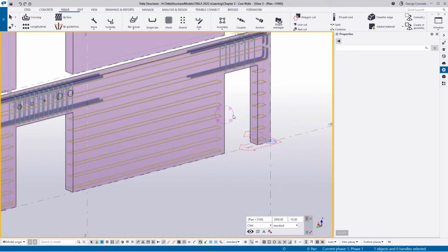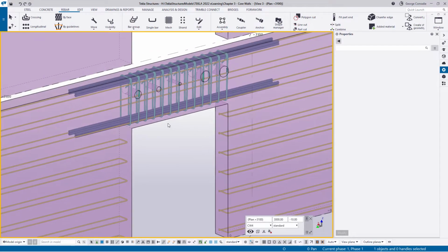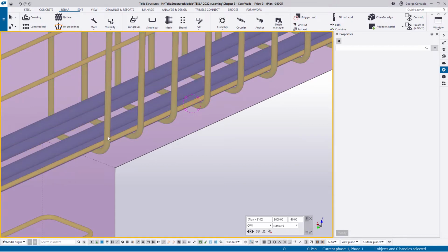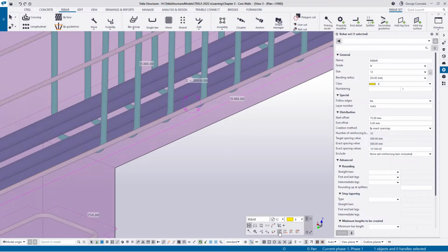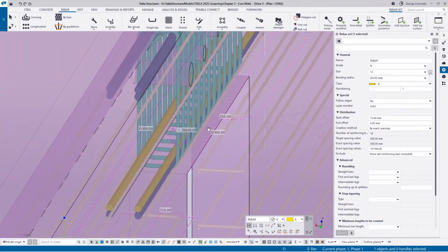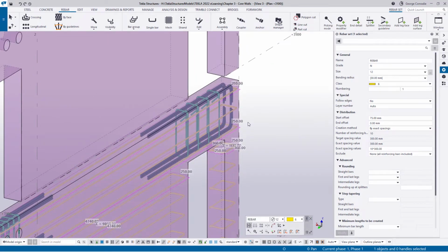Okay, now that those bars are formed and they look pretty good, before we start breaking them up, we need to look at the layering here. Now you can see those bars at the moment are going inside of these legs, and the reason for that is these we inserted before those. Now if I click on this, hover over to our contextual toolbar, and I hover over to the first one that says move to the outermost layer, as soon as I do that, it swaps them around. You can now see the ligatures and the internals have moved inwards, and the horizontal bars of the walls are now the outer layer. And I need to do the same here.